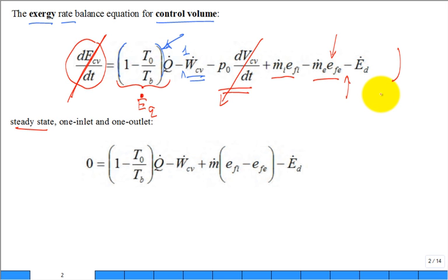There's our Exergy balance equation. Hopefully we can read that equation. True? What do the terms mean? So when it's steady state, 1 inlet, 1 outlet, that mass flow rate is the same, so we can just drop the subscript on m dot. So you find that you have a change in the flow Exergy. The fluid stream is either increasing or decreasing in Exergy as it flows through the control volume. And then this is power in or out, and then the Exergy transfer with the heat. And Exergy could be destroyed. Why would Exergy be destroyed? Because of irreversibilities, just irreversibilities.